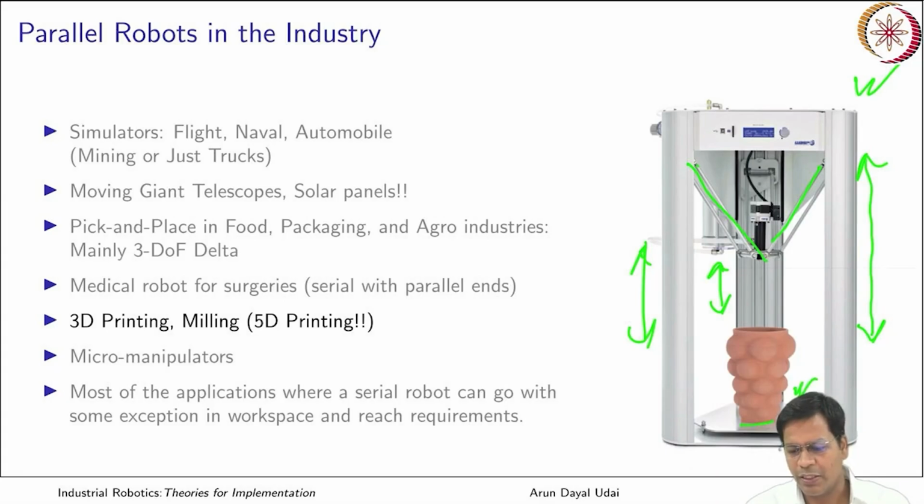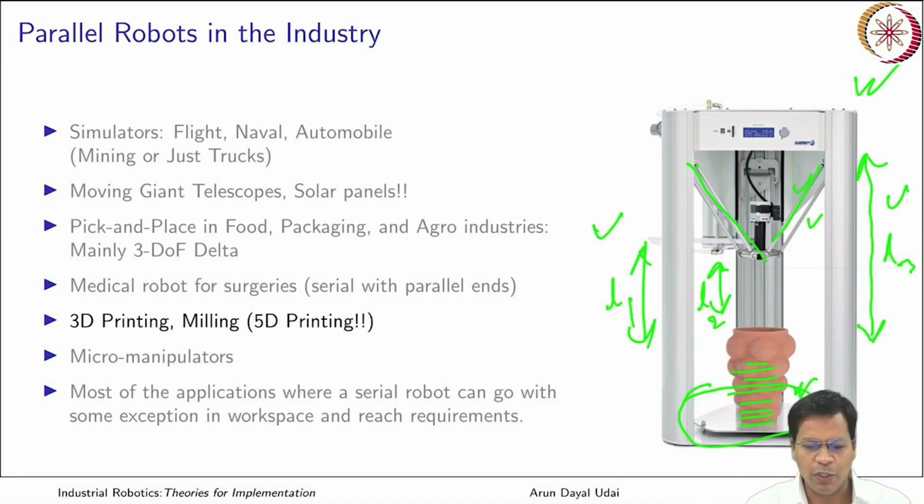As it is built layer over layer, all the 3 links can go up, and by adjusting the lengths of all the 3 links, L1, L2 and L3, which can extend and retract, so those are prismatic joints basically. That is moving this platform, okay, and making it go anywhere in this region. So it can make XY motion like this anywhere, and it can go up and down. It is a 3 degree of freedom robot.